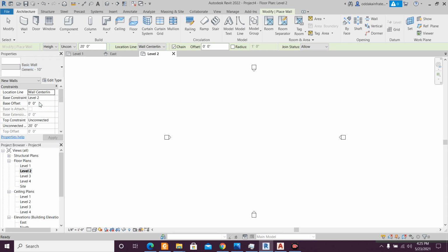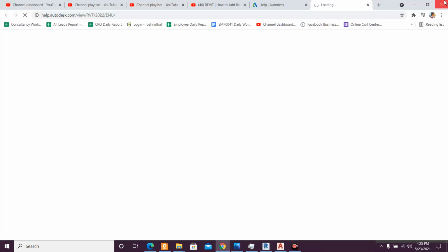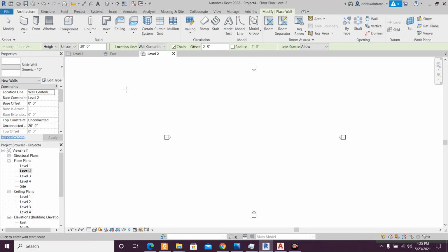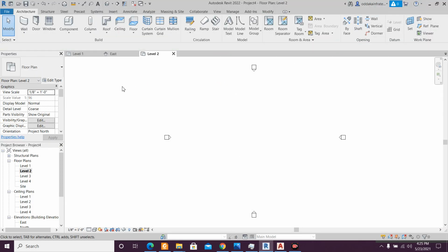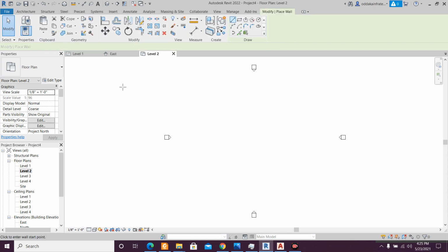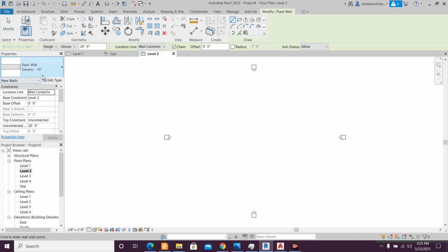And if you are not having the rectangle part, just click on escape. Select type WA once again, and then you'll find this generic 10-inch wall. Make sure to do this as finish face interior, all of them, and this level 2 base height, make this as level 3.